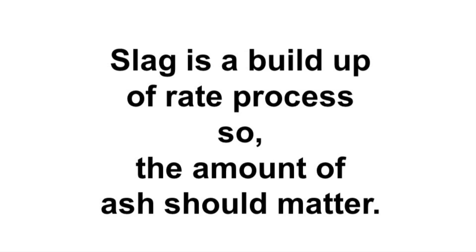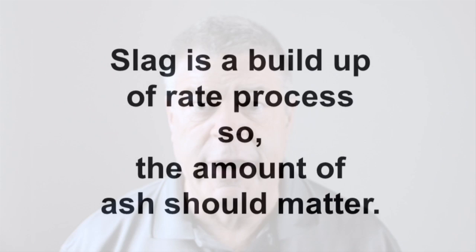What I'm suggesting is that if you take the same ash quality and double the amount of ash, you're going to get about double the slag buildup rate, or it builds up twice as fast, which takes away from the operator's time to deal with slag. So I think the amount of ash is an important factor to consider.